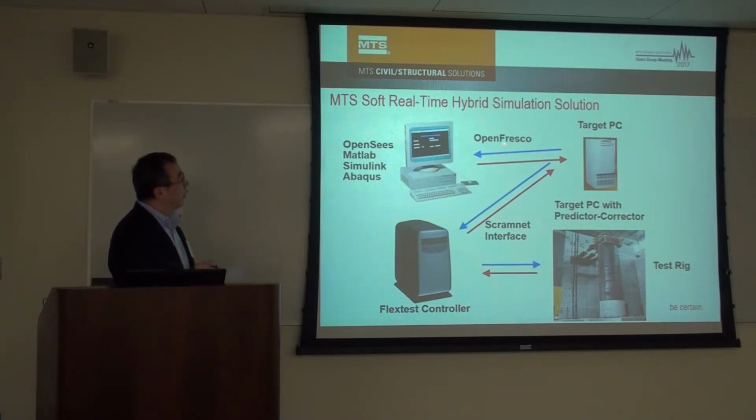So the analysis model can be a regular non-real-time package like OpenSees, and OpenSees sends commands through OpenFresco to a target PC. In this target PC, there's a predictor-corrector model running, developed by UC Berkeley, developed by Andreas.